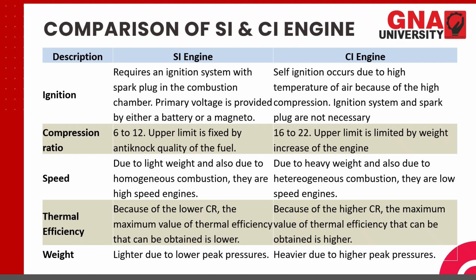Upper limit is limited by the weight increase of the engine. Because you are having high compression ratio, you need to add more material. You need to increase the thickness of the cylinder so as to withstand the high stresses developed by this high pressure.